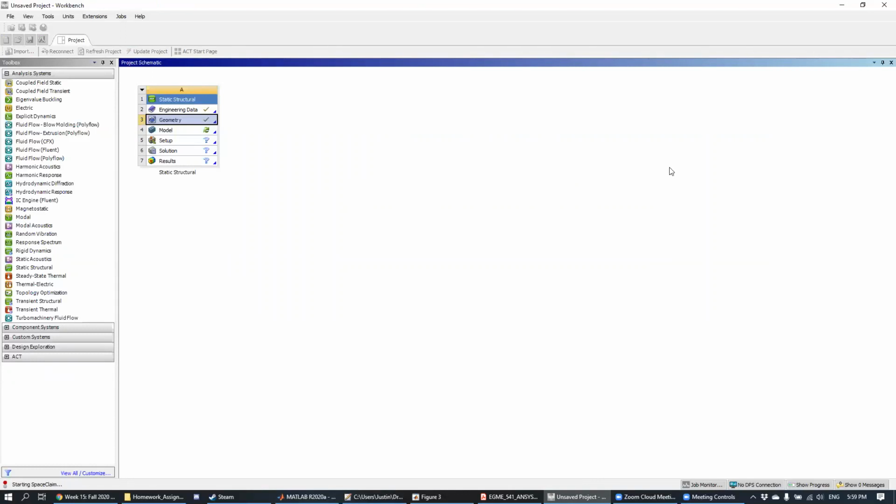Oh, yeah, that's a good point. Chris made a great comment here. If you are using ANSYS SpaceClaim, this actually lets you modify your geometry, whereas the other CAD software, DesignModeler, doesn't allow you to do this. So if you have a situation where you have a CAD and you need to modify it a little bit for simulation, SpaceClaim should be your go-to tool. Yeah, great point, Chris.